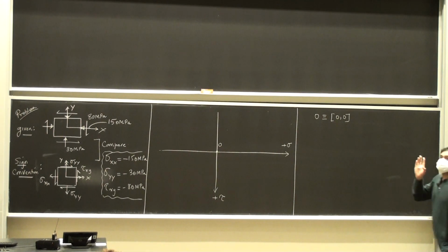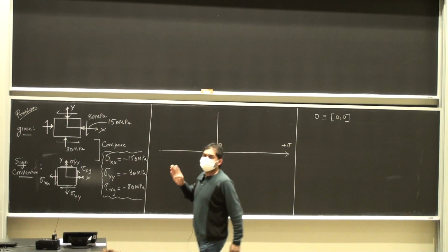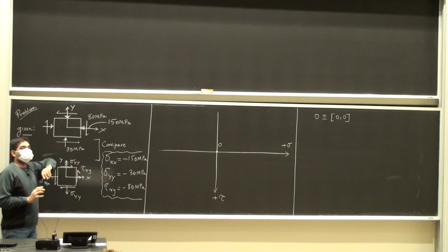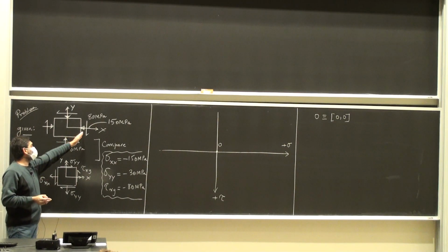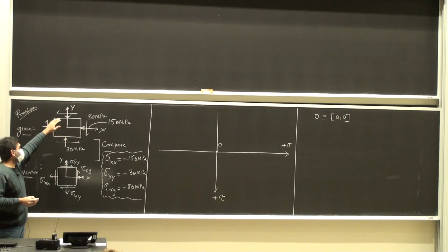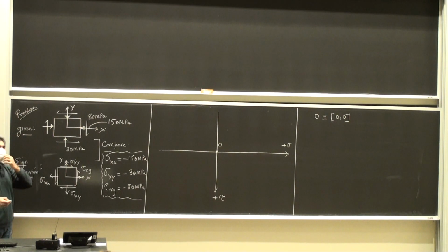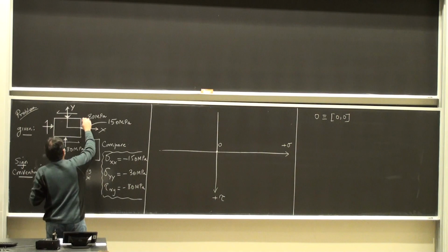Then we choose the side of interest for us. Typically, the side of interest is always the side on which the axes are going to be labeled. So in this case, I can either choose this or that to draw the Mohr circle. Don't worry about choosing this. We typically go with the right side. Okay? Always. So this is my interest.